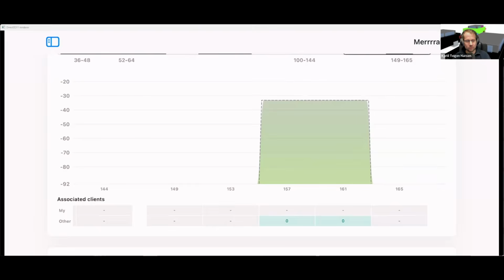Yeah, so usually if you walk a survey and the noise level is measured at like -70 at a place, that would usually never happen if there wasn't some type of interference signal that raised the noise floor that high. Yeah, exactly. Noise level will be based on everything that it can't demodulate, and a proper enterprise access point can demodulate really low. So Keith and everyone else can probably say if I'm wrong here, but Jerry, you have a question?